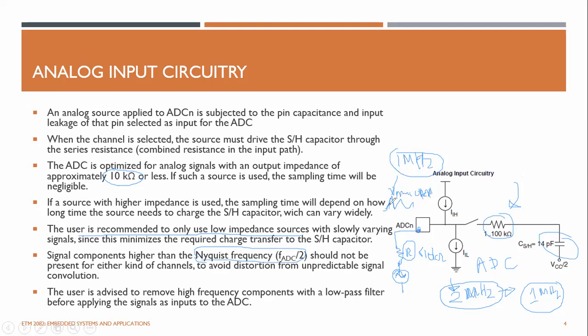And sometimes your analog signal may be coming from a robot arm or any kind of sensor, and it might have some noise, right? In that case, you need to couple this ADC signal using some kind of RC filter to remove the noise and get a very smooth signal, removing these spikes, right? Then only you can get an accurate reading. Otherwise, it will sample this noise as well, which will give you error readings.